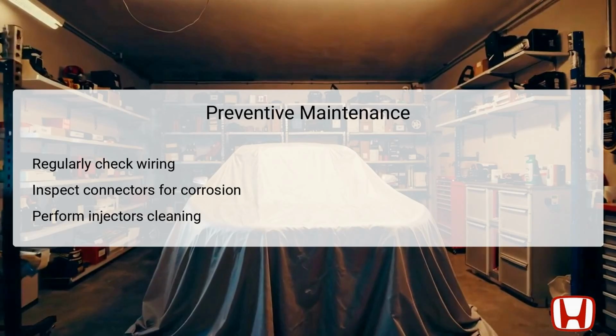Additionally, cleaning the fuel injectors periodically helps prevent carbon buildup, ensuring efficient fuel delivery and better engine performance. Establishing a routine maintenance program can save both time and cost in the long run, ensuring that conditions remain optimal for engine operation and minimizing the risk of trigger faults like DTC P0202.